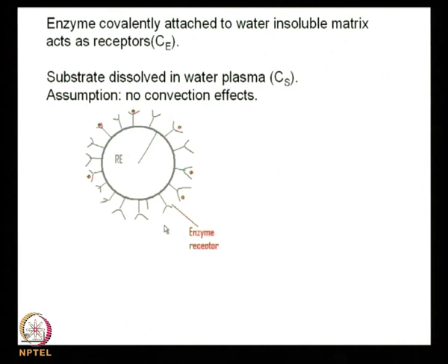The problem that we will always face in this chapter is that any kind of analytical solution or quantification that we try to do would be limited by the fact that the intrinsic reaction kinetics governing the interaction between the enzyme and the substrate is Michaelis-Menten kinetics, which is by default non-linear in nature.